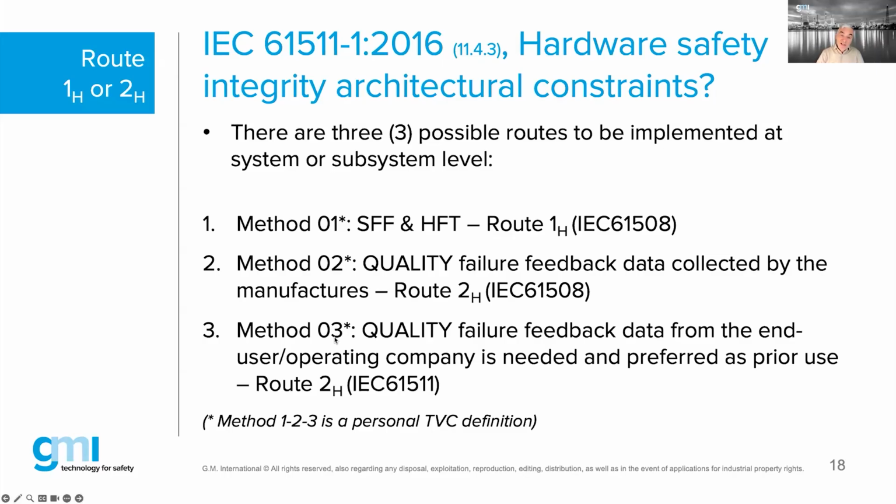When an end user or an operating company is using that data collection, quality data collection, we call this prior use. So both method 2 and method 3 are nothing more than feedback from existing installations, from existing equipment with good failure data records that you can prove. Not just verbally, you need to be able to show some evidence. When there is a failure, did you do a root cause analysis, or where is this data coming from? Can you show us the proof test intervals, data, coverage factors, confidence factors, etc.? So all these questions will actually be used in order to give us evidence that you have good quality feedback data.